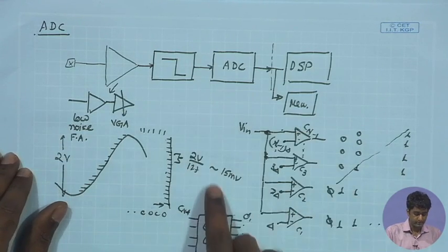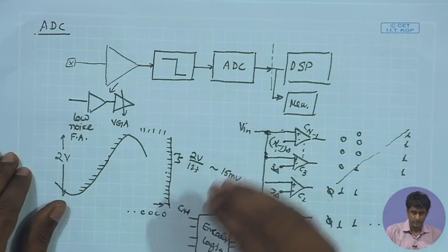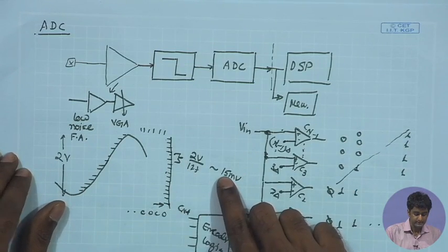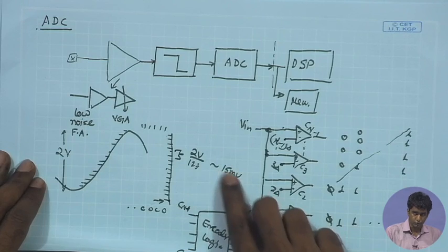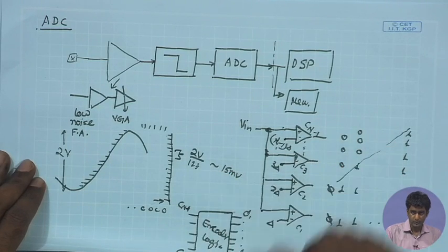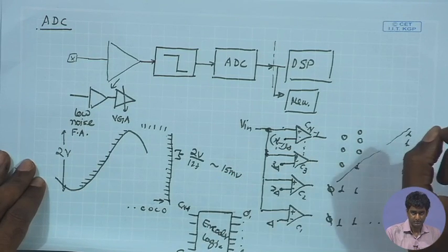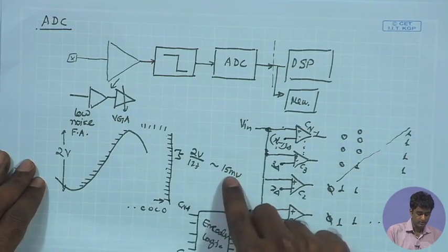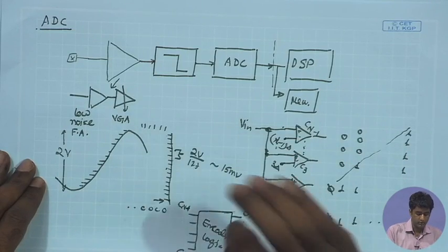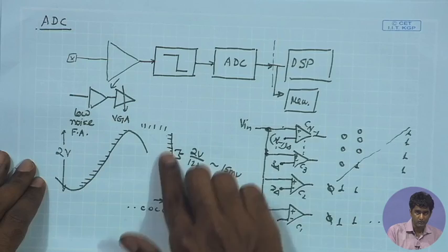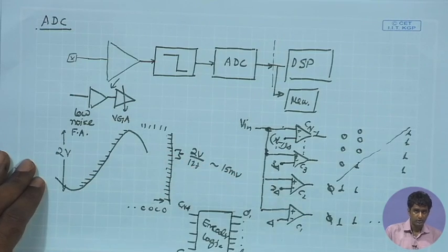That means, if the data droop, or the analog droop, or increase in the sample values is close to 15 millivolt, we are losing 1 LSB of the precision, and we are going to get data which is wrong by 1 interval. So, that is not desirable.